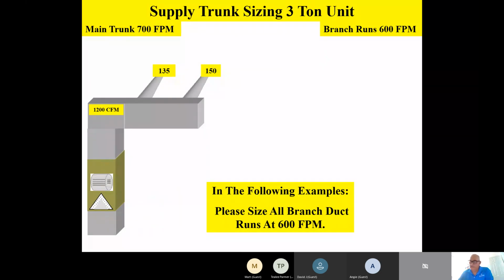So on this next example, this 150 CFM, we should size our takeoff up to 7-inch round duct. Any questions or comments? Is everybody good?